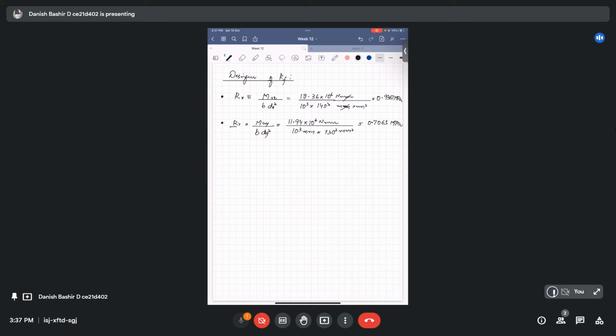Let me write a formula for the pt required. pt required upon 100 is equal to Ast required upon bd, which will be equal to fck upon twice fy, into 1 minus under root of 1 minus 4.598 R upon fck. This is the basic formula.